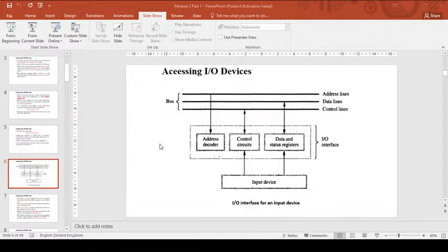So when the compare operation output is 0, that means the entered character is the same as the carriage return. The subtract operation will give you the answer 0 if both operands are the same. In that case, it will go to the move instruction. And if it is not equal to 0, that means the entered character is not the same as the carriage return. It can be either more than that or less than this. We are not bothered. We just have to check whether it is the same. If they are not the same, then the result of the subtract operation will be non-zero.